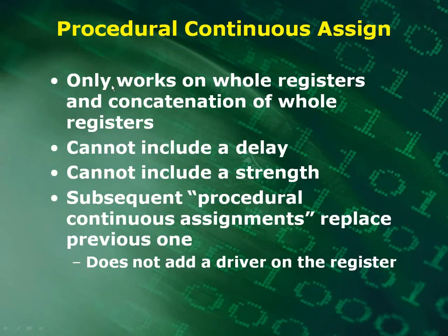Okay, it only works on whole registers and concatenation of whole registers. You cannot include a delay or a strength, and subsequent procedural continuous assignments replace the previous one, and it doesn't add any type of driver onto the register.